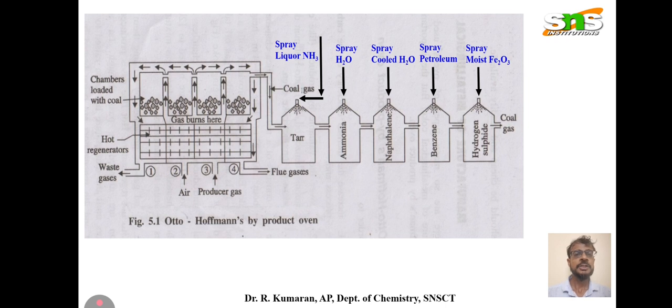and it is subjected to carbonization inside the chambers, which are made of silica bricks. They can withstand more than 1000 degrees centigrade, and the material is further subjected to the carbonization reaction, and the remaining gases flow to the side towers, where the byproducts are recovered.